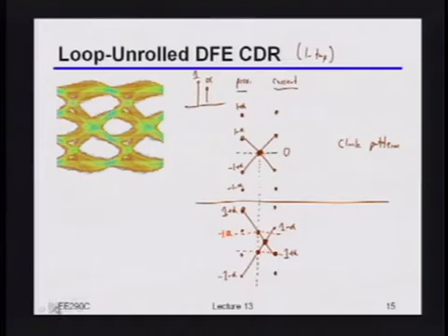Okay, and the way you can see that is the peak-to-peak swing here is 2. All right, so you go from 1 minus alpha to -1 plus alpha. Excuse me, the peak-to-peak swing here is 2 minus 2 alpha. Okay? Whereas here, the peak-to-peak swing is just 2. Okay? Because you go from 1 plus alpha to -1 plus alpha.